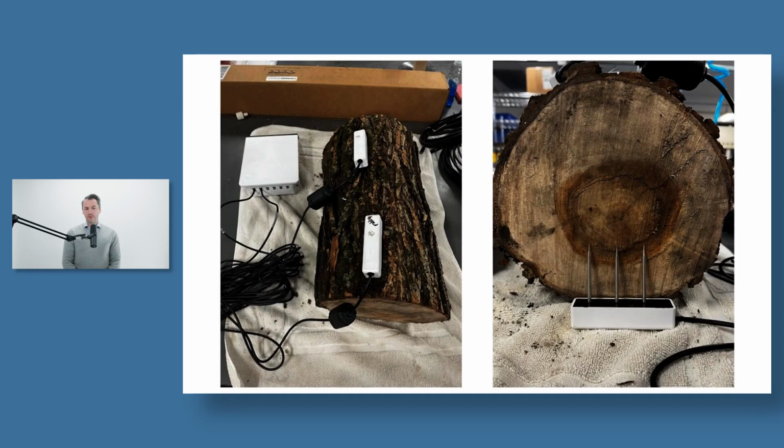Circling back to the issue of calibration, I'm going to present data from stem water content, and it's going to have the default calibration from these sensors applied. So we know that the absolute numbers are incorrect. We're still working on these calibrations, and that's because it's a challenging thing to do. What we have found is that it takes a long time, and you have to be very careful about slowly drying these logs out while you're getting values from your sensors and weighing them to get the known amount of water and how much water has been lost. There's enough difference even from one tree species to the next that you can't just have a general wood calibration for these sensors. You need to have a species-specific calibration. So part of the challenge is making sure that we have representative samples and that we can do this repeatedly in different tree species to have good calibrations.